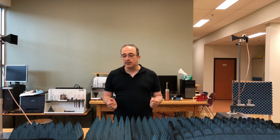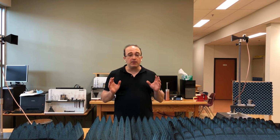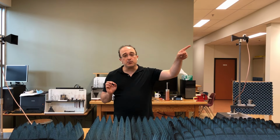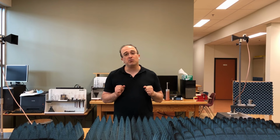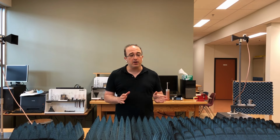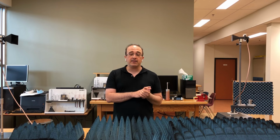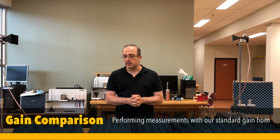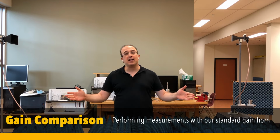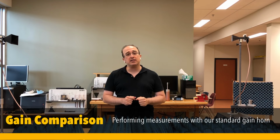Now, to do that, we're going to do another measurement. And if you remember, we had this small horn antenna, and we calculated the gain of this small horn antenna in a different lab. So we know the gain of this small horn antenna at the frequency of operation, which is 10.52 gigahertz. So we keep the same distance as our measurements. It was 1.6 meters in these measurements that we have.